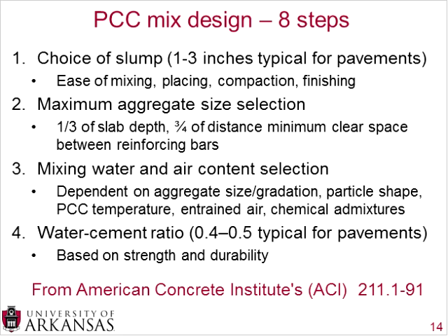So the first step is to determine the slump. And when you're looking at pavements, you're typically looking for 1 to 3 inches of slump for your typical mixture. And what does the slump influence? It influences the ease of mixing, placing, compaction, and finishing of that pavement surface.